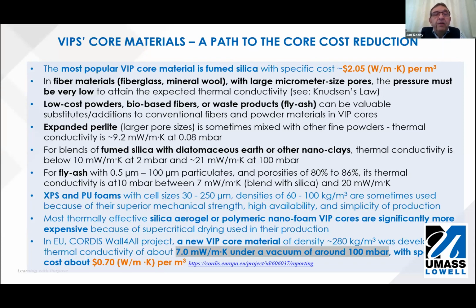Another very interesting group of materials are fibrous materials, like fiberglass and mineral wool. They have quite a large size of pores, but they are non-flammable, they perform very well at high temperatures, and at a very high level of vacuum they can achieve extremely high levels of thermal insulation.